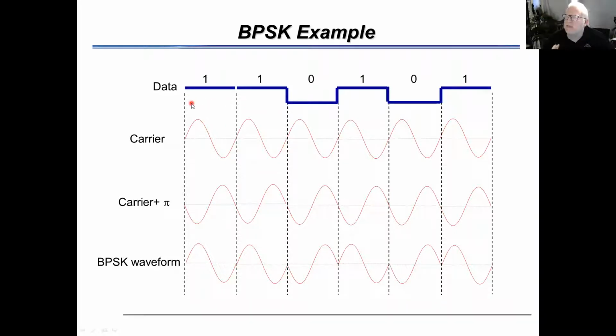what we call the TP, or the duration of one bit, is, for example, 1 second. So in this BPSK model, you are transmitting 1 bit per second, because in this duration, which is the TP, you are transmitting only one bit. In other words, your symbol is 1 bit. So you are transmitting 1 symbol per second, and your symbol includes only 1 bit, so it's obviously 1 bit per second.